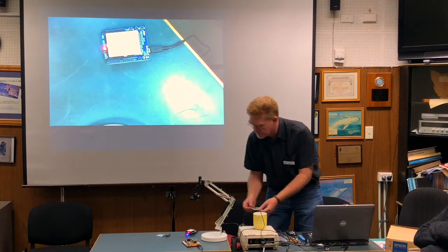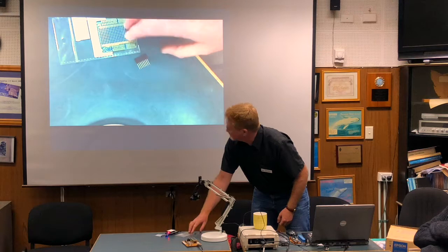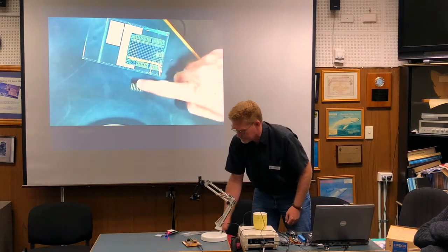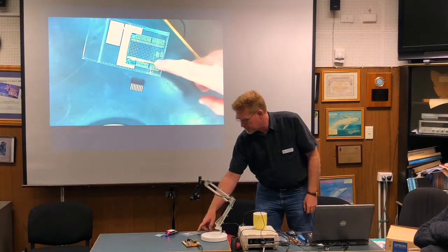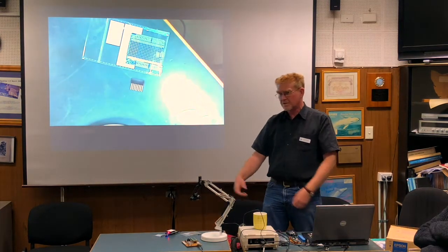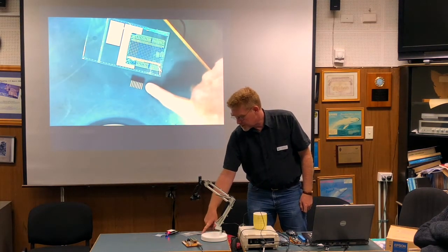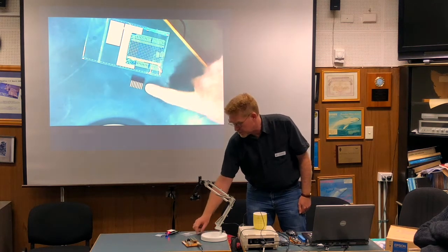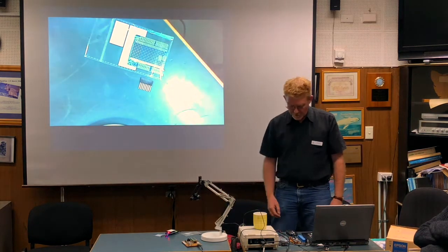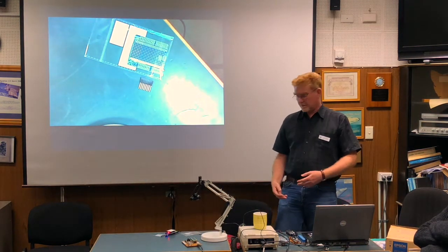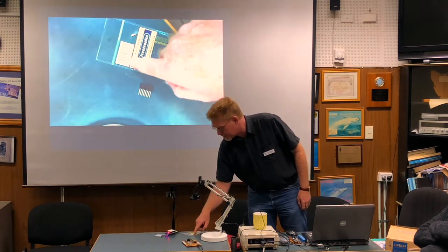Other ideas for shields? One of my favourite ones is basically a board with lots of holes. But there are of course the usual minimal traces in here to take the pins from the headers and route them somewhere useful so you can then solder onto them without having to jump through. The key with the headers they use to connect is that they've got very long legs on them, so you put them through one side, solder over these, and get the legs coming out the bottom. Not too hard to hunt down these days, everyone on eBay sells them, but this one was a purchase from my friends at Jaycar, complete with the Jaycar compartment on there.